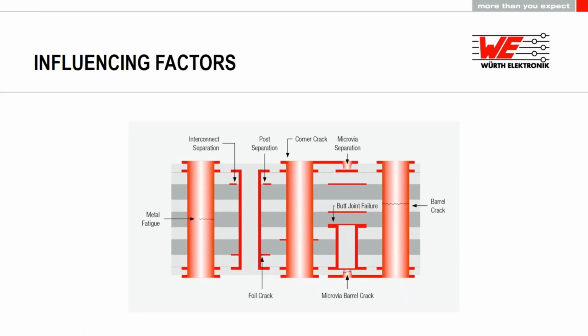And this leads to the effect that the increase of the copper thickness leads to an increase of reliability to a certain point. And after that point, it will go down again. And what the optimum point is depends on the specific design, on the build-up, on the different layer connections, and so on and so on. So it has to be found out or tested for each stack up alone. That's how you have to do it, because no design is like the other.